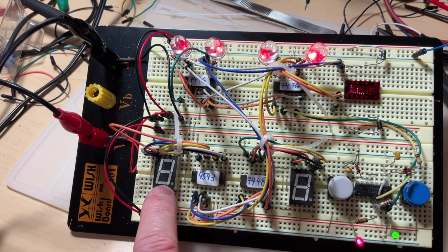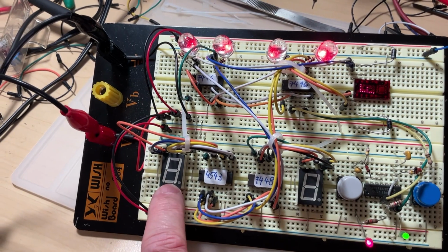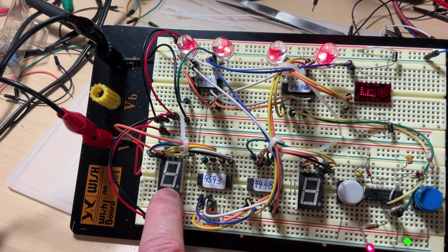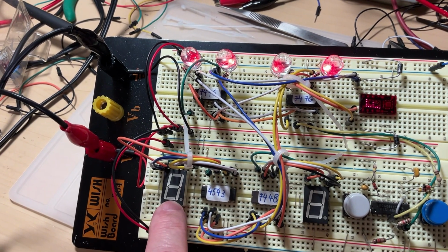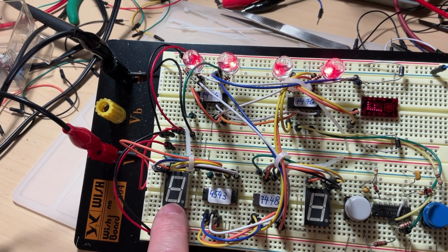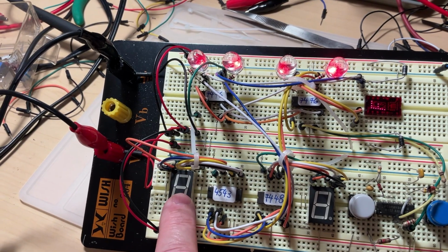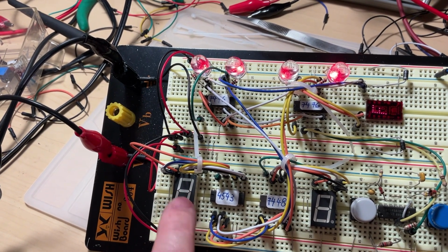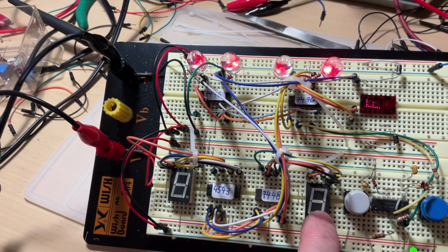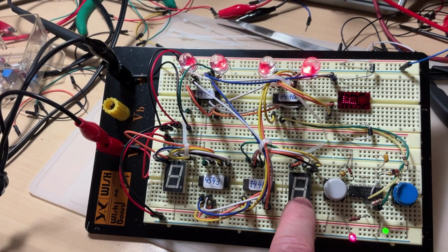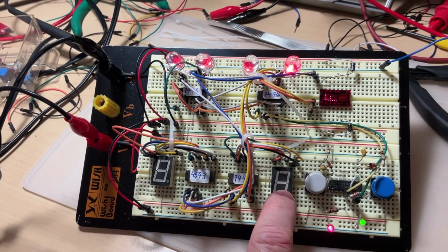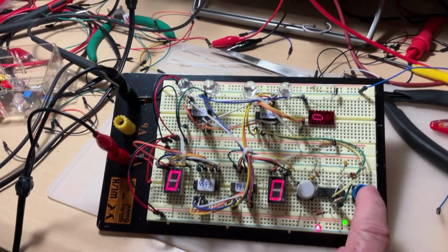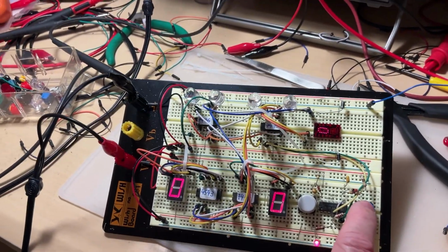The decoder attached to it may not be able to recognize any combination bigger than 9. So between 10 up to 15, the display remains blank. So there are different reasons why the displays may remain blank. And the fourth reason, yes, the display may effectively be defective, which is not the case, because if I press it one more time, it goes back to 0.